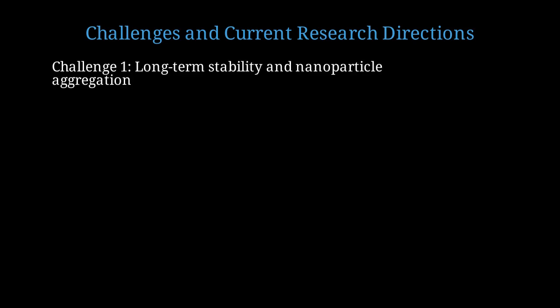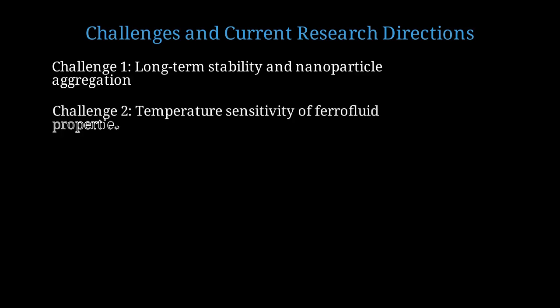Now let's examine current challenges and ongoing research directions in this field. Challenge 1 is long-term stability. Over time, nanoparticles may aggregate despite surfactants, degrading magnetic properties and fluidity. Challenge 2 is temperature sensitivity. Both viscosity and magnetic properties vary with temperature, affecting performance across environmental conditions.